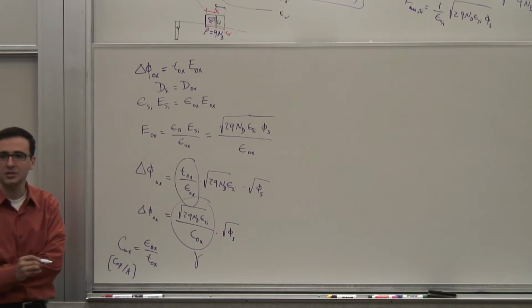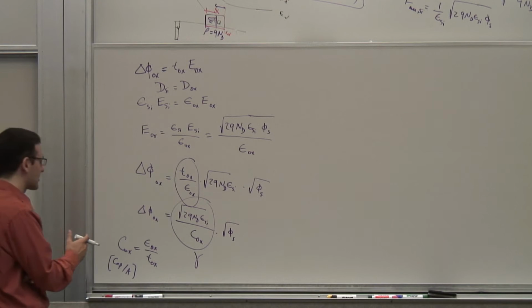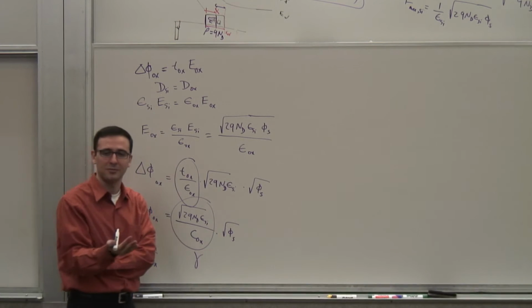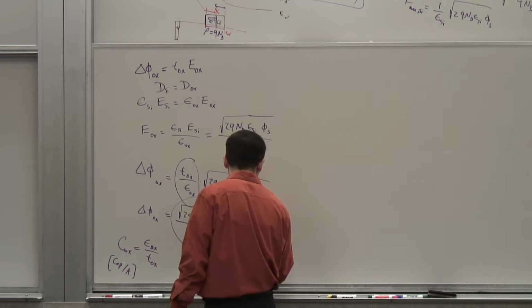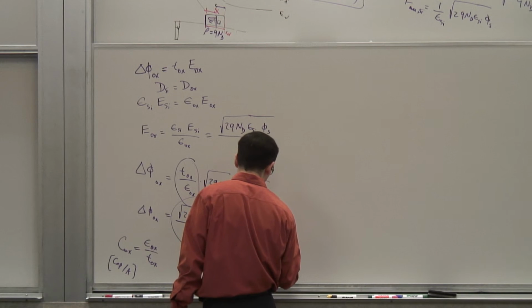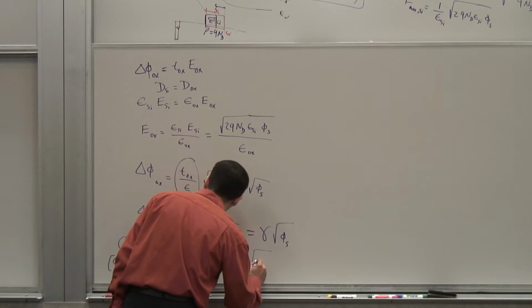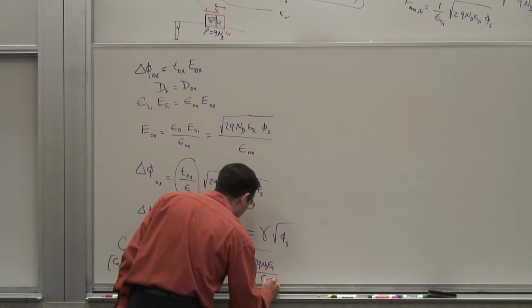This has nothing to do with the emitter injection efficiency. So in the context of MOSFET, it means a completely different thing. Just lack of creativity, I guess. Alpha, beta, gamma, always. There's a lot of other Greek letters. But anyway, we can write gamma square root of Φs. And gamma, by definition, is square root of 2qND epsilon silicon divided by Cox.